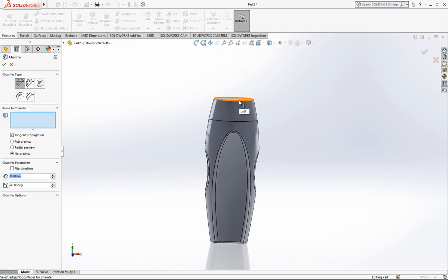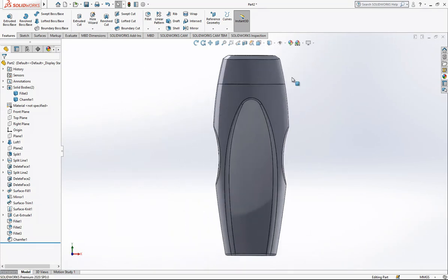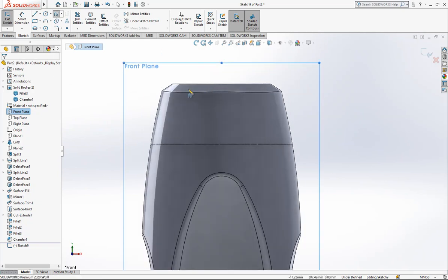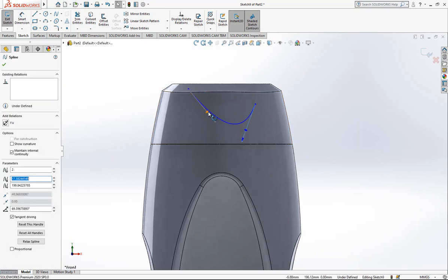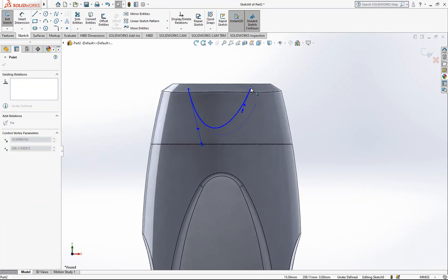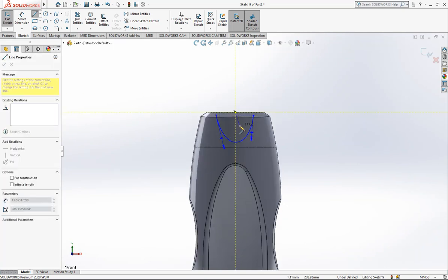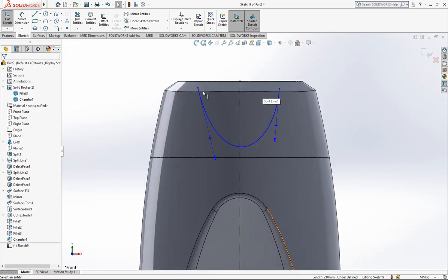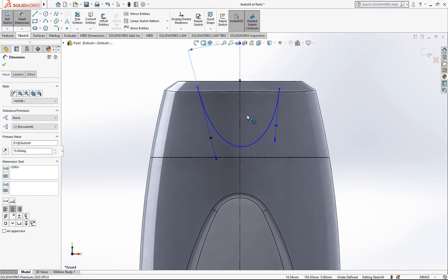First there will be a chamfer, a big chamfer, like 4 millimeter. And then later I'm going to create here again a spline, the same idea. Mostly I'm using splines with 2 points, starting and final point. In fact, when you use more points, it becomes harder to handle, and you can use them, but just here it's an example tutorial. That's not so important. 15 by 15 our